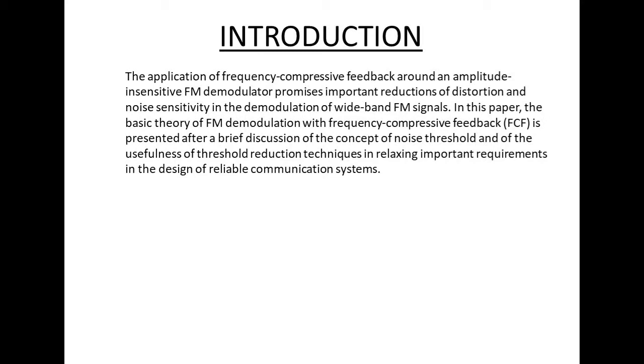The application of frequency compressive feedback around an amplitude insensitive FM demodulator promises important reductions of distortion and noise sensitivity in the demodulation of wideband FM signals. In this paper, the basic theory of FM demodulation with frequency compressive feedback (FCF) is presented after a brief discussion of the concept of noise threshold and of the usefulness of threshold reduction techniques in relaxing important requirements in the design of reliable communication systems. Let us go to the next slide.